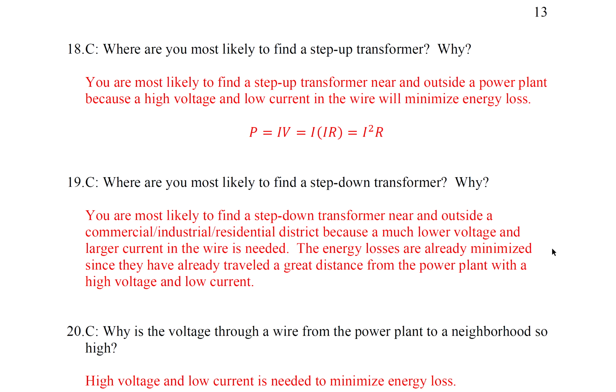Question 18. Where are you most likely to find a step-up transformer and why? It's outside a power plant because high voltage and low current in the wire will minimize energy loss.